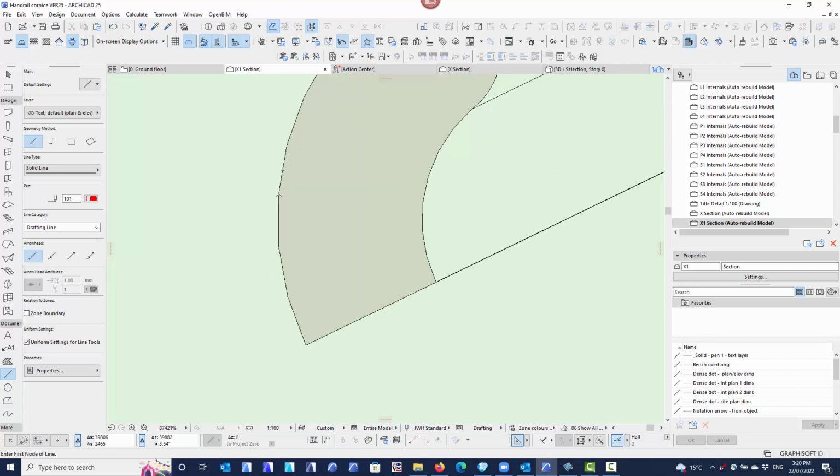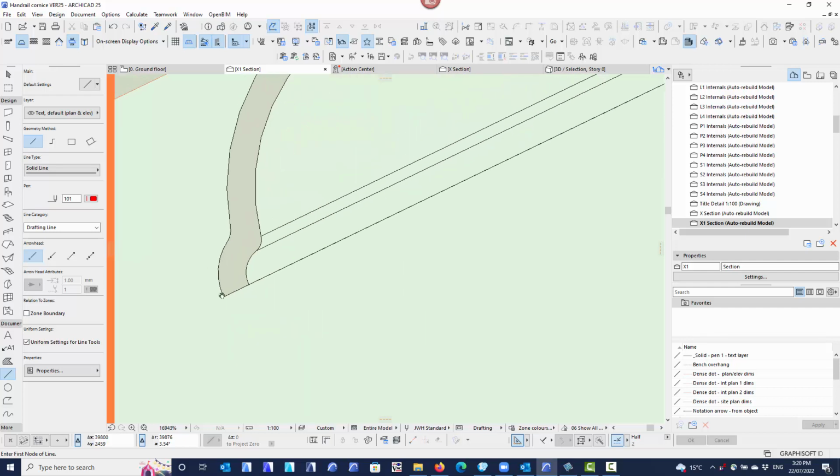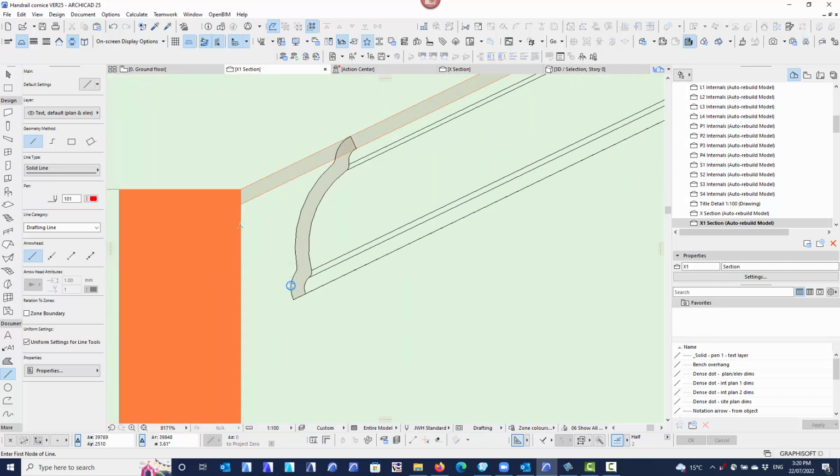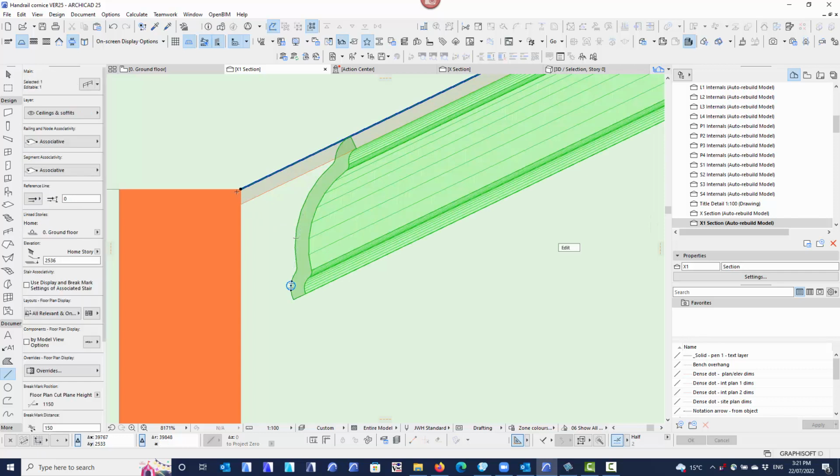Sometimes you'll get the node like that. You will see the little tick to say there's your node and you can select it. Sometimes you can't and you need to just go here and activate the guideline there, activate the guideline on that edge, and then you'll get a node that you can select. Now the problem is, as I say, it's not this point that we need to stretch, it's this selection node. So it's actually this node here.